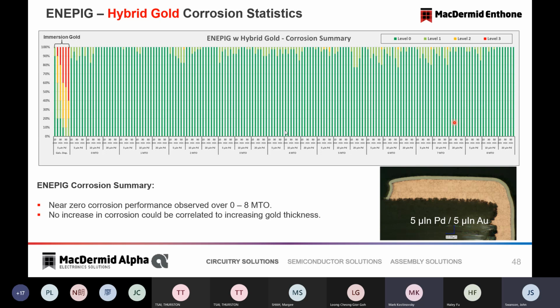Then I'm begging for one more question. When you do this deposition with the hybrid gold, right? Yes. You are obviously oxidizing hypophosphite, and are you saturating the surface of the palladium with the elemental phosphorus from that reaction? Are you saturating the surface? No, you're not oxidizing hypophosphite to the phosphorus level, are you? Because palladium obviously forms with the phosphorus really nice intermetallic too.